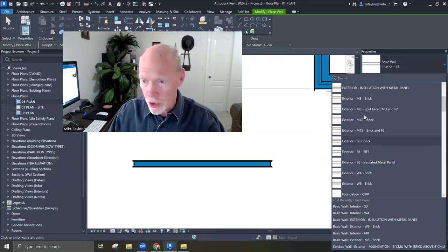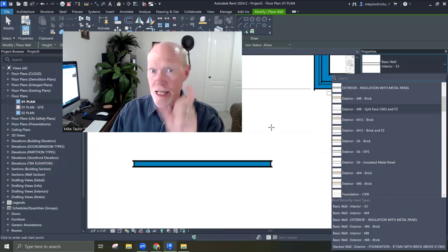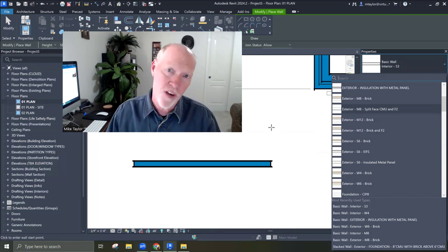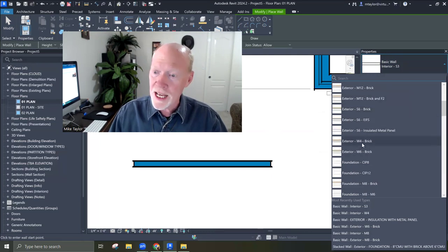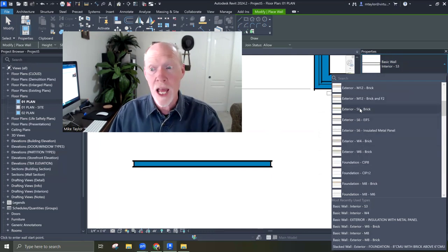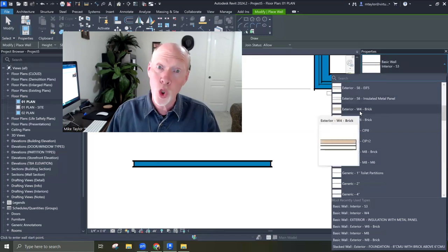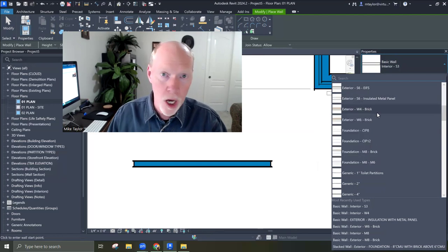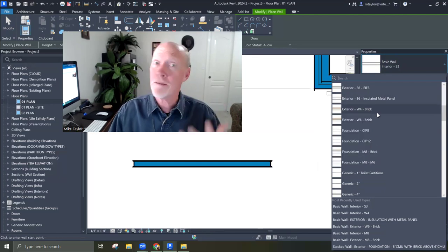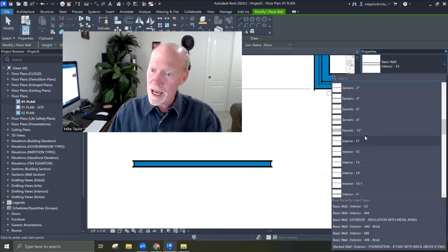But the key I wanted to show you is there's an M8. That is a masonry nominal 8 inches. We know it's 7 and 5/8, but nominally 8. So that's what I put in the name. And then M12s, S6. What's an S? An S is for steel studs, so a 6-inch steel stud. And then I've got W's for wood. Makes sense. W4, W6. We know that 2x4s are not 2x4. They're 1.5 by 3.5. But nominally, that's the name of them. Anyway, let's just get past that.